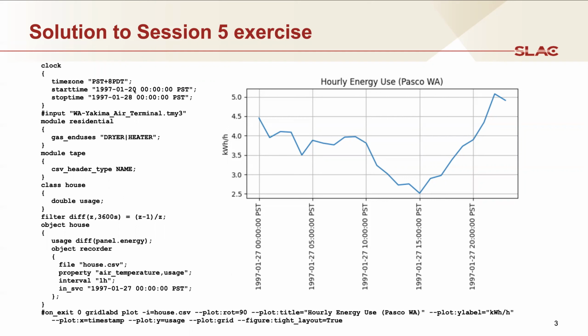Since we're looking at one house, it's probably not going to need to be a full week, but I'm just in the habit of making these a week. It's sort of a safe interval. By the time a week has elapsed, all of the potential errors that might accrue from incorrect initial values would be gone. They would be dissipated and no longer part of a simulation output, and so you wouldn't be so worried about having those kinds of errors creep into the results.